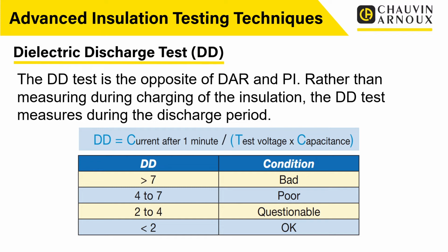I believe this is better for detecting certain faults, particularly within multi-layered insulation. So there are applications where this would be better than others. And as I've said before, sometimes people will apply all of the tests, or a couple of the tests together, just to collate the insulation and make sure that they're all giving a good reading, rather than a lower reading on one where you're getting good readings on others. That might indicate something that you need to investigate further, shall we say.